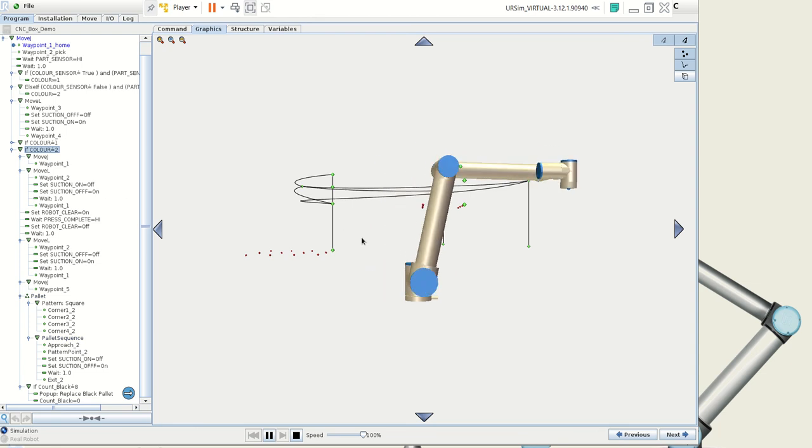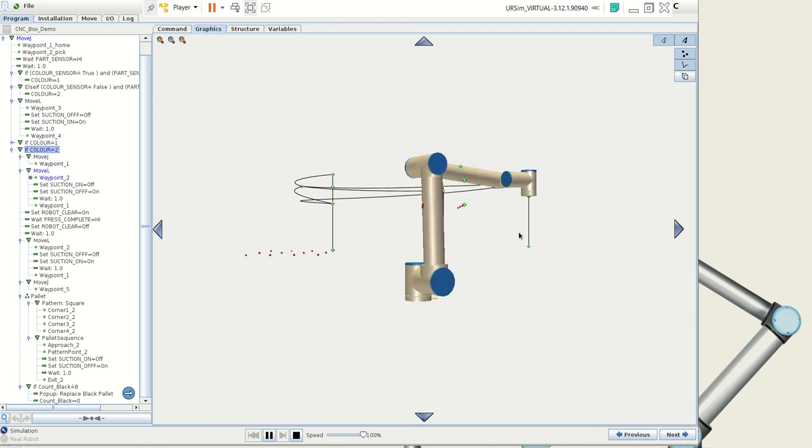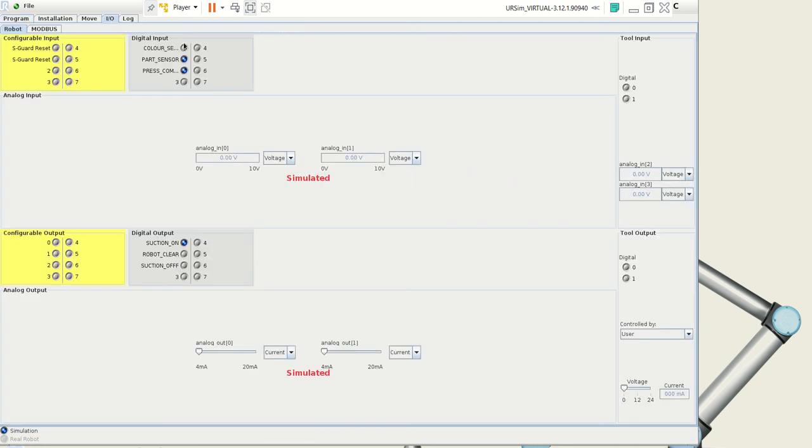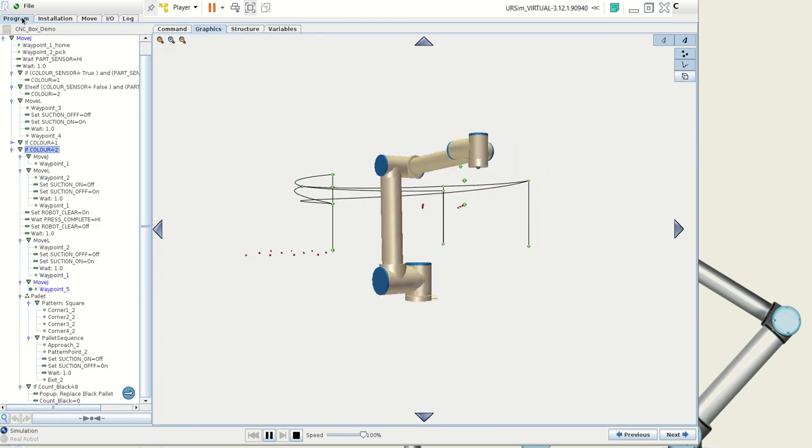Again, you could look at going through the speeds and some of the accelerations of the robot joints as it's moving. But overall, I think we've used the Move L in the proper locations. We've used Move J where it's needed, and that's our full system. So we're just going to look at the final aspect of this, which is adding in a little bit of safety I/O and some safety commands to it, just to give us as close to the full experience as possible of what we do with the robot.